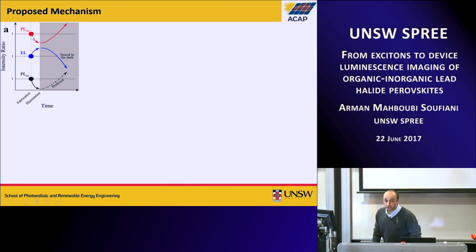The PL shows anti-correlation. After illumination it drops and over time increases. The PL at short circuit condition, I showed that after illumination it drops, but we predict that it increases over time because when you lose the contact, the carriers cannot be extracted during short circuit condition measurement. They recombine and you have higher PL intensity.